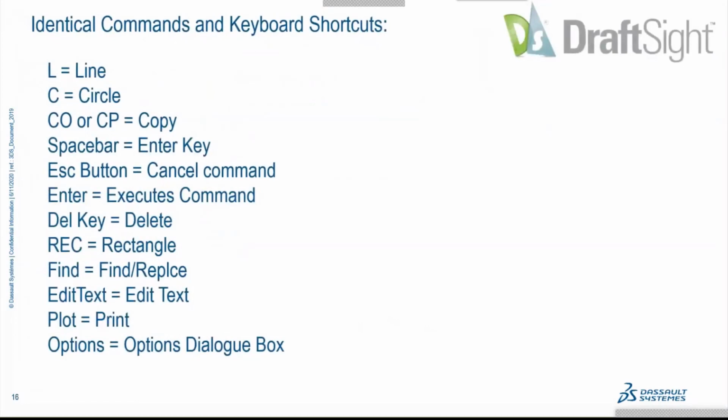Okay. If I go into this one here, this one has some more identical commands, of course. If we look here, we can always cancel just like we do in AutoCAD. We always can hit the familiar escape button, right? Hit the escape button to cancel command. Spacebar is your enter key unless you want to change that. But out of the box, it's set up the same way. Of course, line is the same. So all these are very similar. These are just here for your reference.